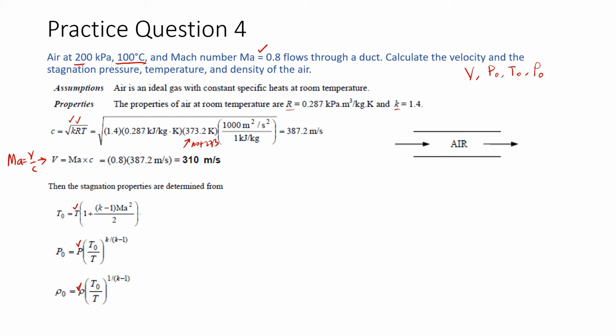Hang on, we don't have density. We have temperature, we have pressure. We have K, Mach number. So you have to find T naught first. We have 421. So with that, you bring it here. We have this value. We have the static temperature. Again, everything has to be in Kelvin. K, of course, you have that. Substitute, and we get this as the stagnation pressure.